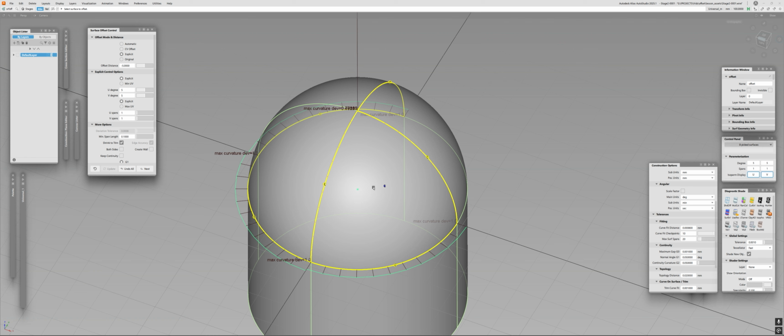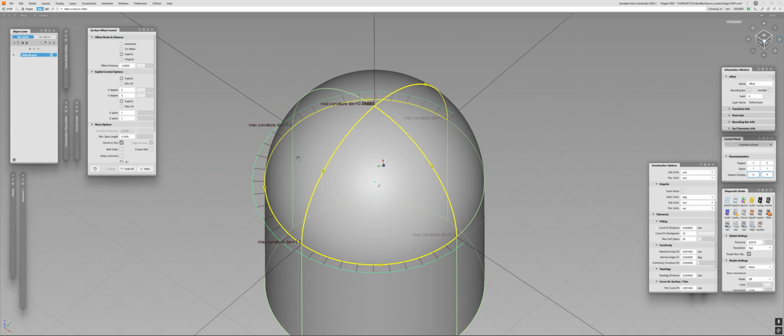And when it comes to the periodic things like cylinders or spheres, the CV offset will not work. It will never work because the periodic surfaces, by their nature, demand a very specific acceleration. The acceleration rate is the same, but the scale is different. So when you offset, you really need to reconstruct them. That's why we are using the automatic approach with explicit, where we can slightly manipulate and change the amount of degrees to help Alias do the job.